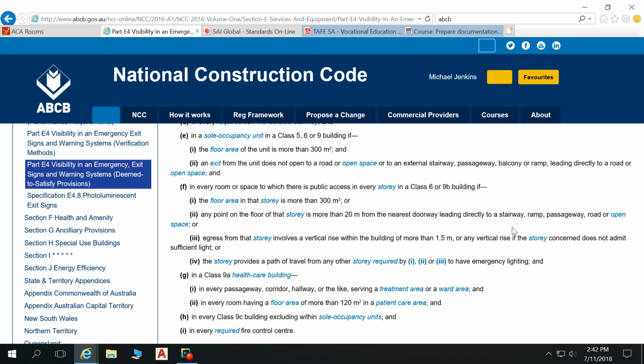So what we'll need to have is things that are visible here, and we want those things to be visible from everywhere in the building. It's not just that we want this exit to be visible to some people and this exit to be visible to other people. Both exits need to be visible because they have to have that option of 2 exits.